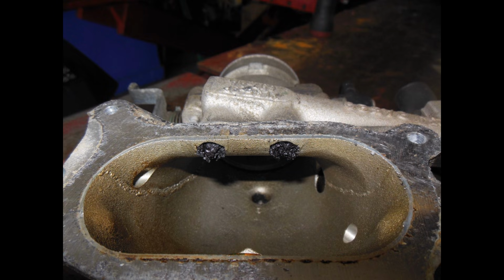And even though I pointed it out to him 4 different times that, in my opinion, based on all the testing I'd done, it's probably this throttle body being clogged, he just insisted it was, and he tells me that he ran a mechanic's wire through it and it was fine. Even though these ports take a hard right turn, there's absolutely no way you can run a mechanic's wire through that thing. The only way to properly do this is to take it off and clean it.